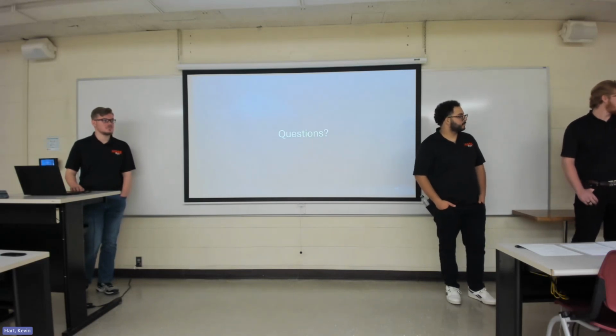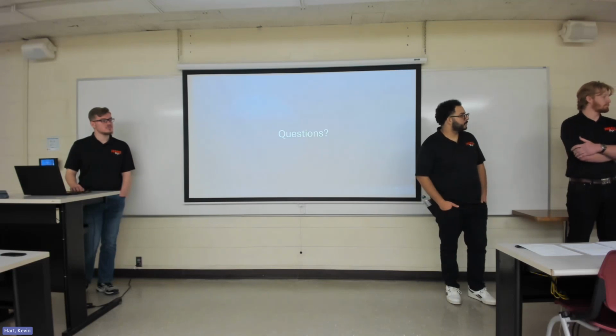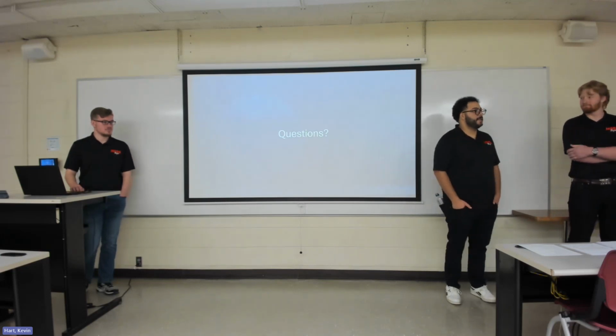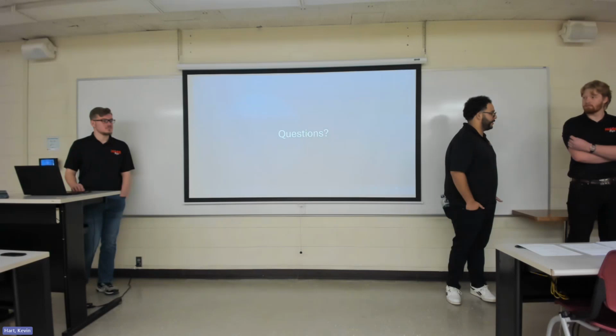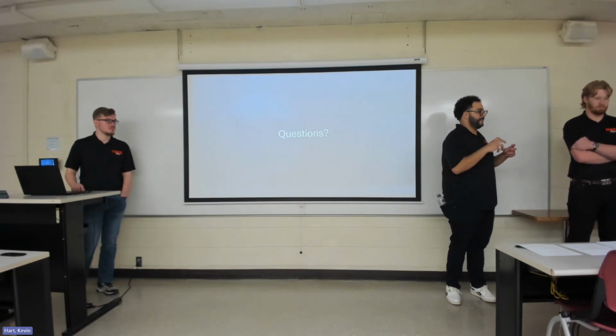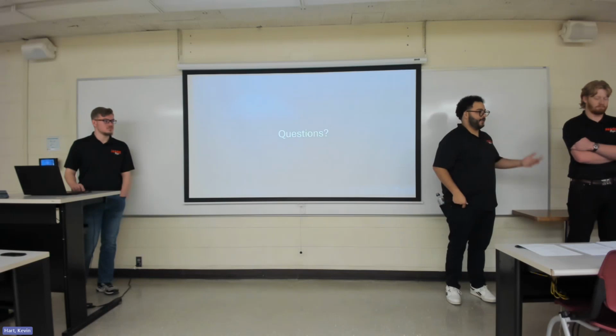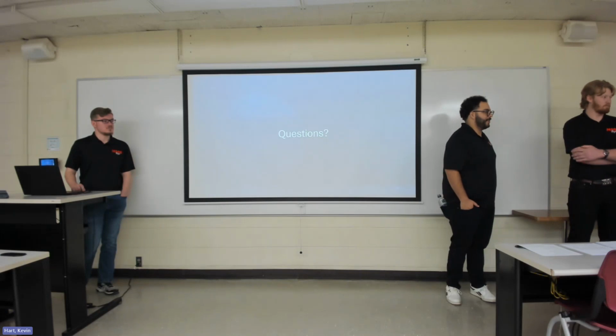Sure. I only have one question. You started with the design goal of 30% lighter and 50 hours of life. Does the design accomplish that? As of now, yes. In the drive shaft alone, it's a 65% reduction. With the gearbox, it was even greater, I believe. And then even more on the axles, we went from solid CVs that were really heavy, purchased off the shelf, to what we have now. I don't have the exact number, but we've definitely reached that goal.